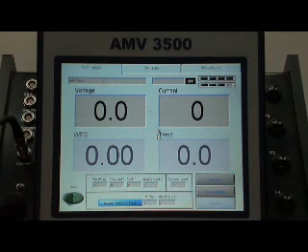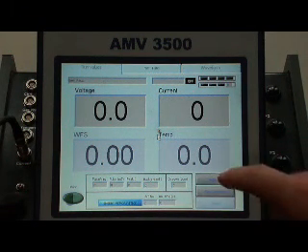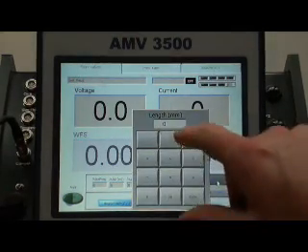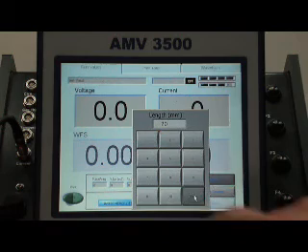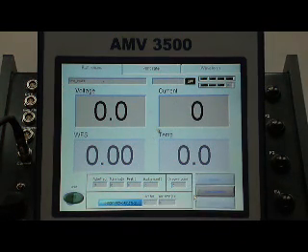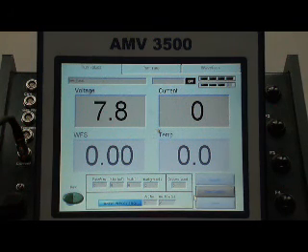And that might be just part of the first pass, it might be a segment. So if it was the end of the segment, we can enter a distance. And we'll now have a heat input calculated just for that segment. The arc starts.